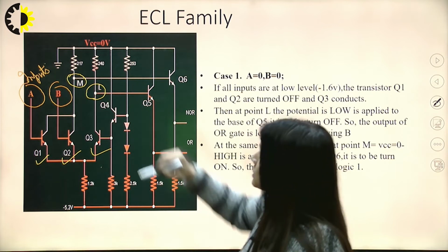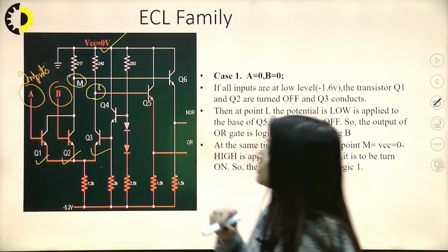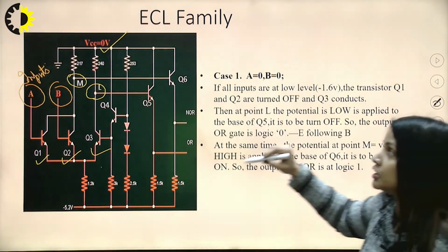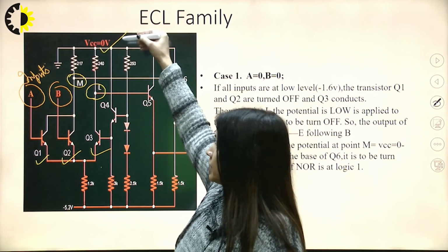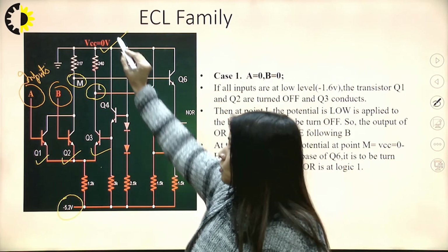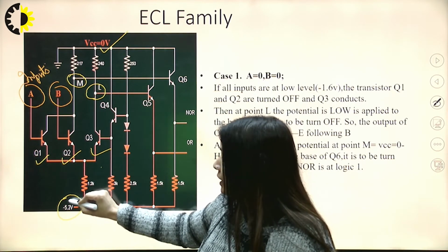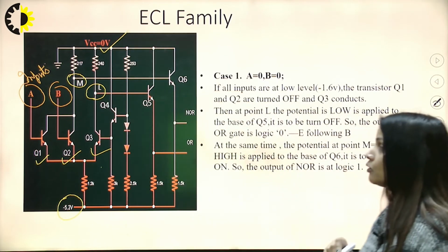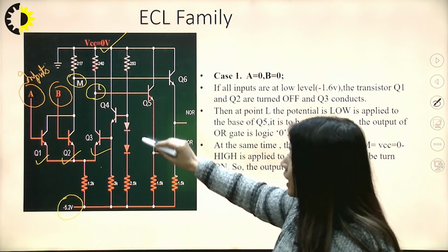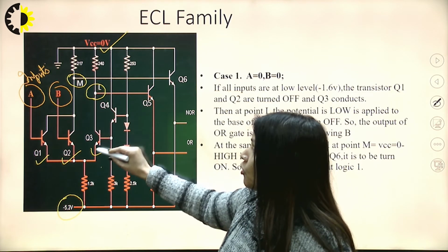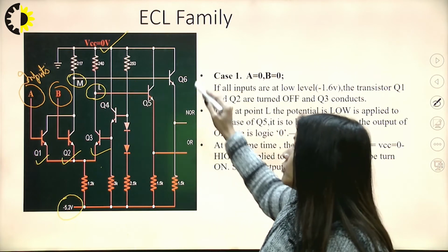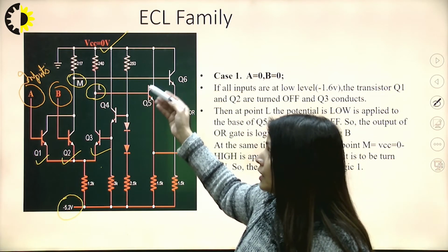Okay. This VCC is 0 volts, right? So this VCC 0 volt, we can consider it as a logic 1 or plus 5 volts, and here this is minus 5.2 volts. So here this 0 volt is comparatively much higher than this minus 5.2 volt. Okay, these are the biasing resistors which we have taken. These are the resistors, and based on the Q3 to be on and off, we will see where the current is going and which of the circuit are on and off.